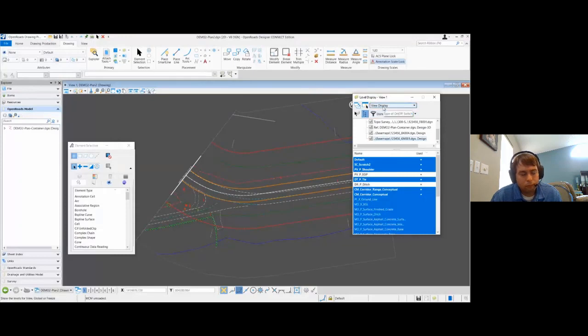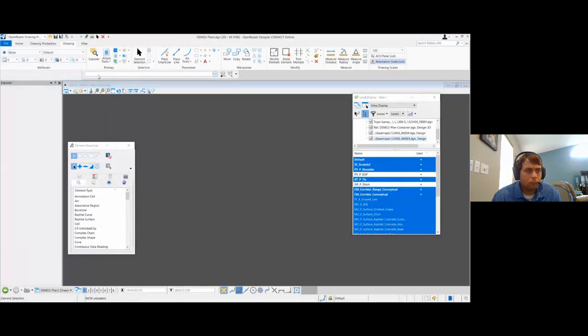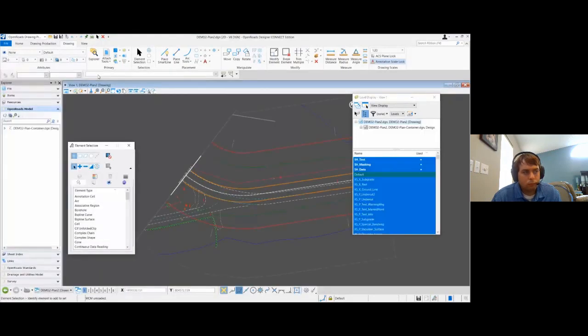This is where you can see it get a little complicated, but this variable is only controlling global display, but I already had it turned off by the view display, which this variable wasn't controlling. So if I save settings and reload the file, maybe this was a good example to show. It's staying on now. So it does get a little tricky there, but if you stick to the global display for your stuff, then you won't run into that. Oh, well, I turned it off for view display before.